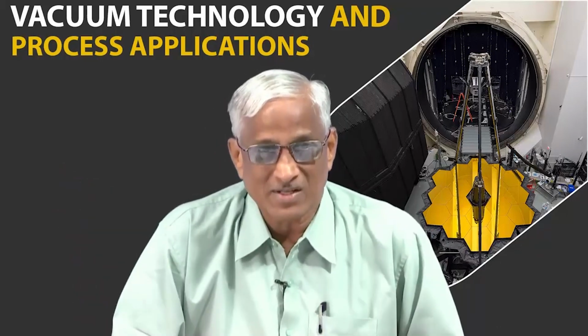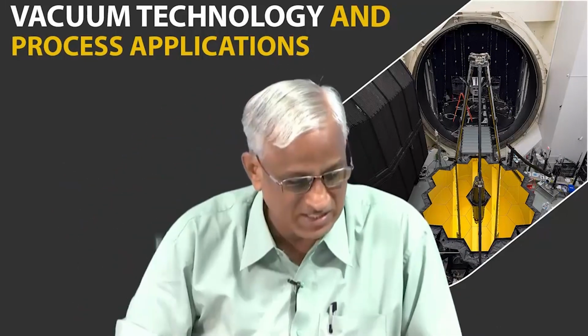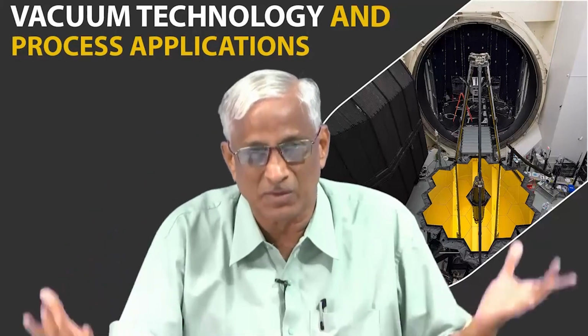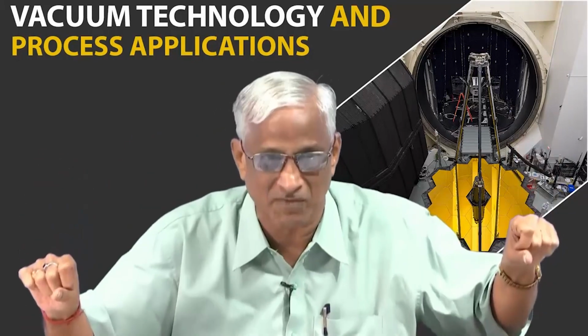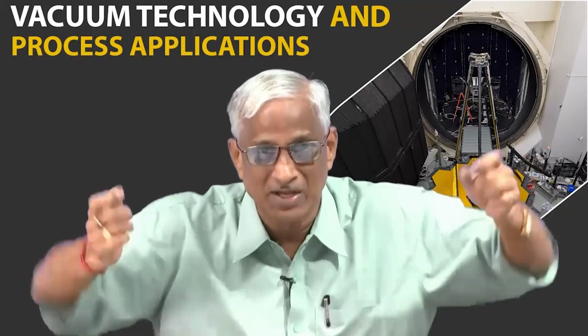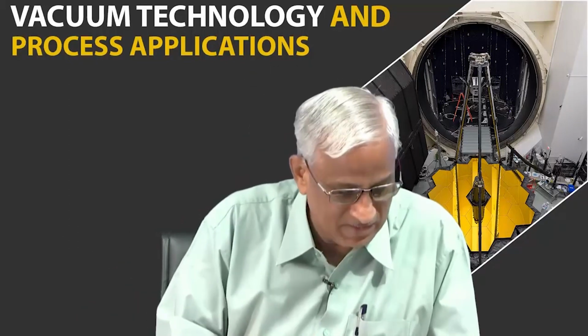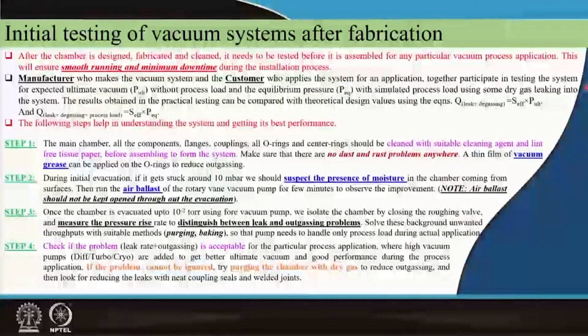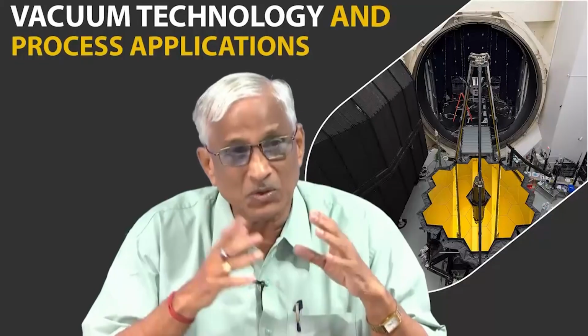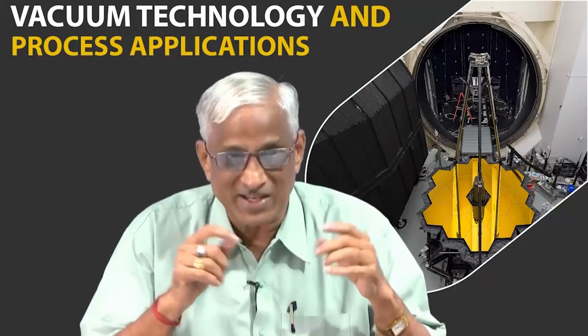Vacuum itself will be able to give enough pressure, particularly for all the vertical things. Horizontal things you need to give a little bit of support also. If heavy things are coming, then seals may get little wedges. So, you should be careful in giving supports. Normally in UHV people know how to do all these things. And if the problem is still there and you are not getting very good vacuum, this normally happens in UHV, then you try to suspect the leaks in the welded joints and leak check them.